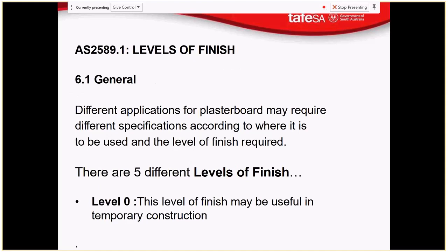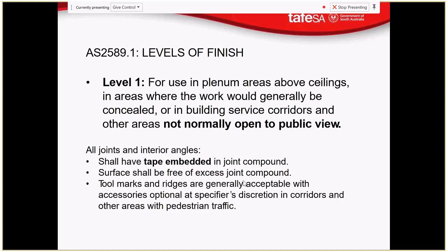So different applications for plasterboard may require different specifications according to where it's used. There are 5 different levels of finish. Level 0, this level of finish may be used in temporary construction. Nothing more to say. So that's just slapping some lining on there to stop dust or whatever transferring through.